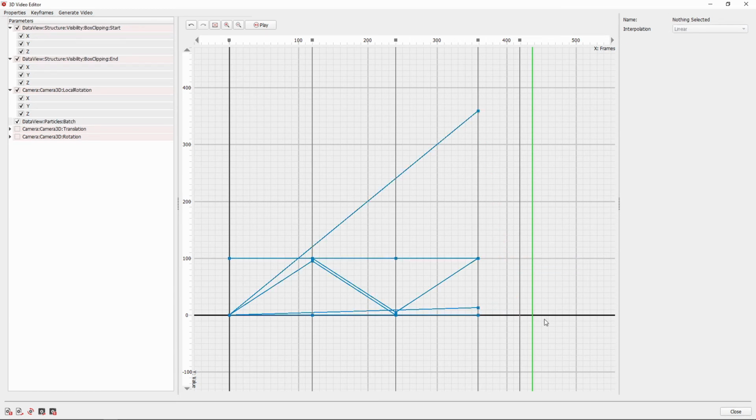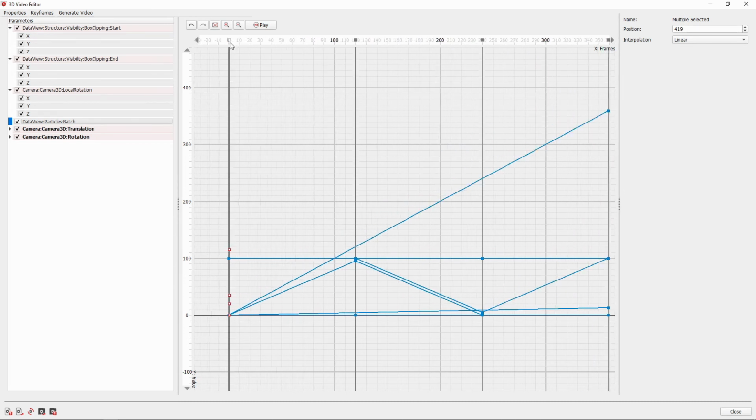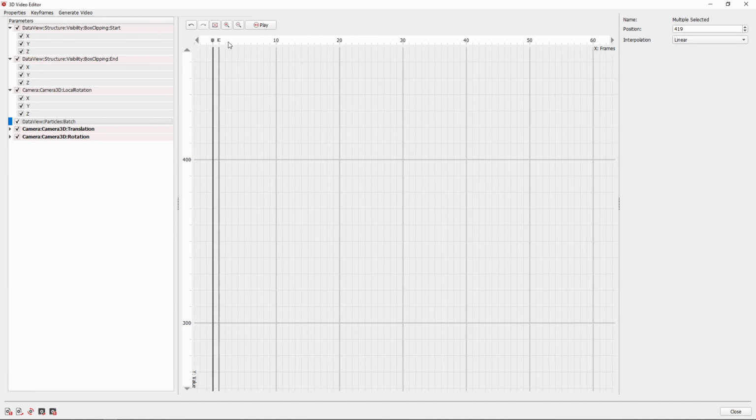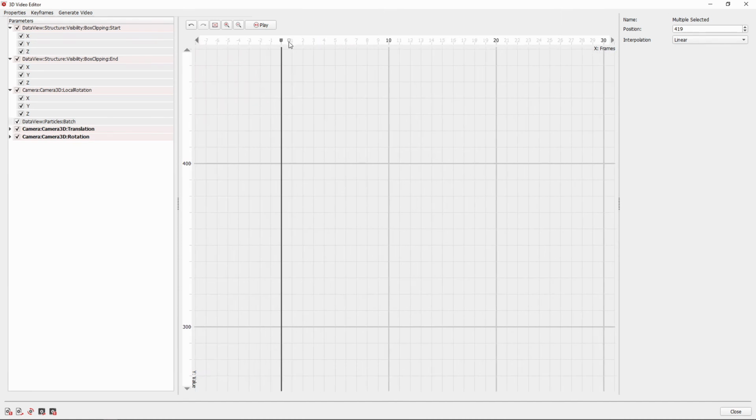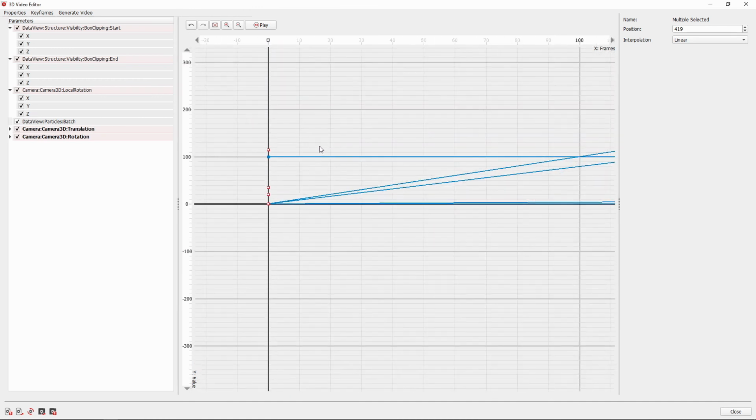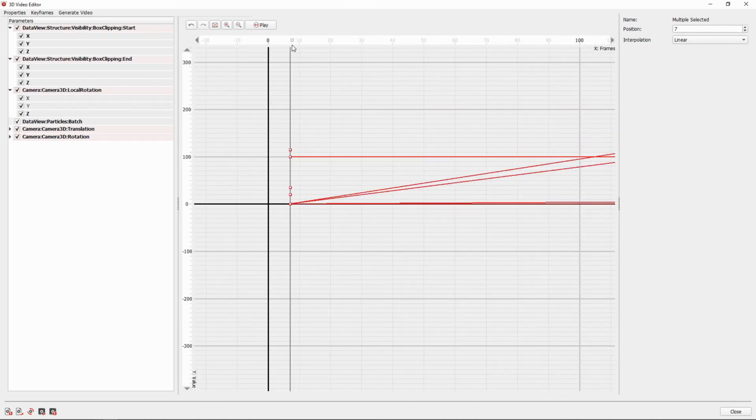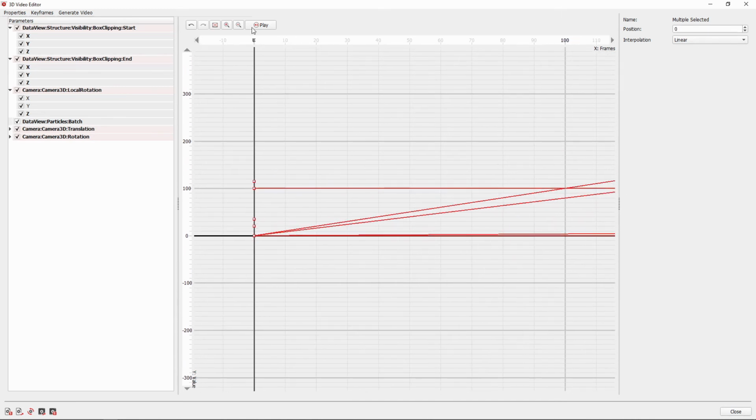We make the parameters translation and rotation visible again and move the keyframe on which the remaining control points are located to frame 0. We zoom in a little bit to make sure that we have hit frame 0 and readjust if necessary. When we are ready, we can now move the keyframe 0 to the side, again as a control, and see that both keyframes have been merged. We make sure that everything is back in place on frame 0 and center our view.